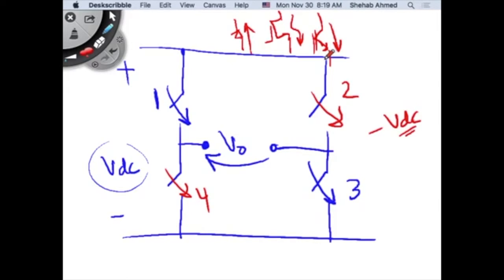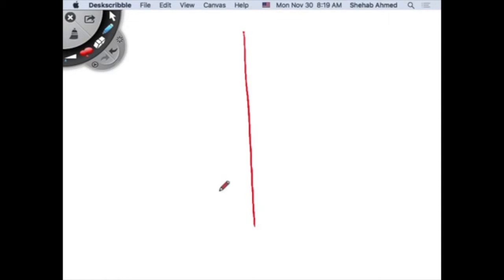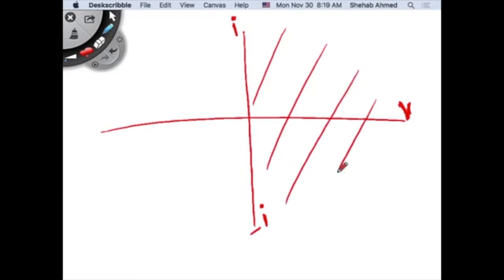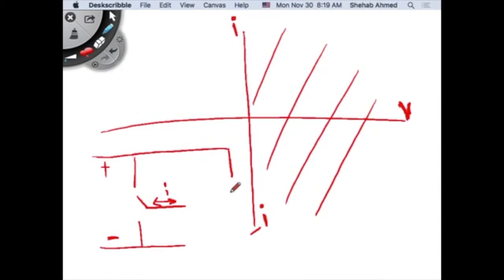And we know that also from the chapter 1 slides, remember that table that we used to go back to. Here we had the same polarity for voltage, and then the polarity for current was flipped. So since I have my representation for the single pole double throw configuration here, and I have current here that is bidirectional, right? This is my current. Current is bidirectional. And the voltage is unidirectional. This is my inverter, right? This is my full bridge or half bridge inverter representation.